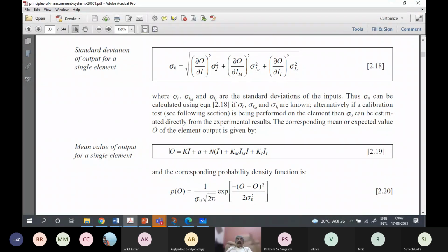Possibly because you have another temperature sensor in the oven, which is much more accurate, on which you have a lot of confidence, and using that you think you have created 200 degrees, and then you are trying to see what reading some other temperature sensor gives. But that 200 degrees centigrade that you have measured using another sensor itself may have some variation.